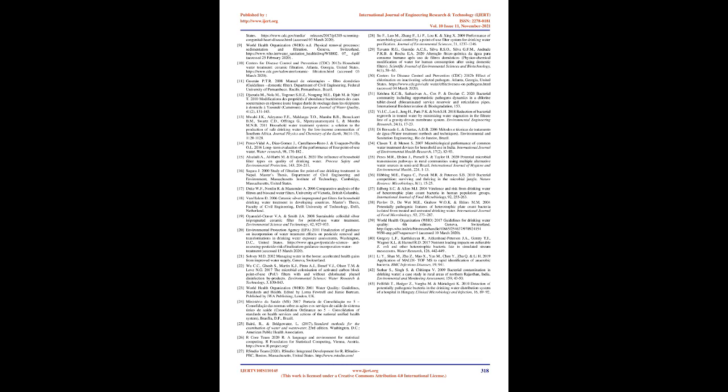Although the outcomes of this research indicated that the use of ceramic candle filters, traditional or with activated carbon, to treat contaminated and chlorinated water sources were very effective against thermotolerant coliform and enterococcus, the detected increase in the concentration of heterotrophic bacteria, especially when these filters were filled with activated carbon, may be of concern.